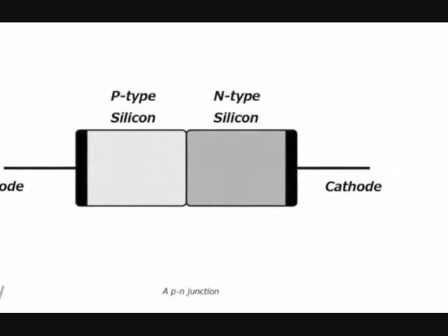To create the P region, impurities such as gallium, aluminium, and boron can be added to the semiconductor material. Due to the addition of these materials, a large number of holes are created in this region. The P region in a diode is known as the anode, and it forms its positive pole.